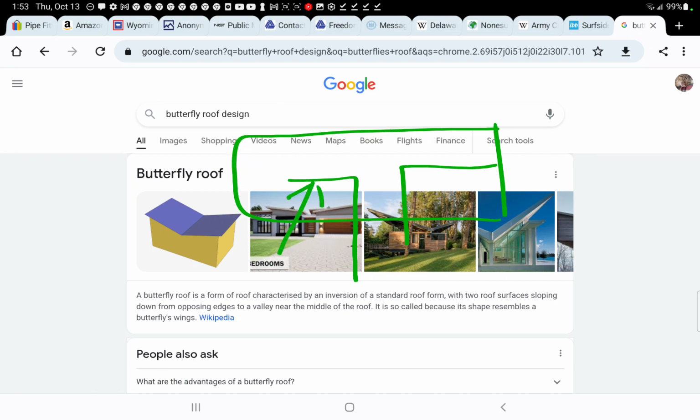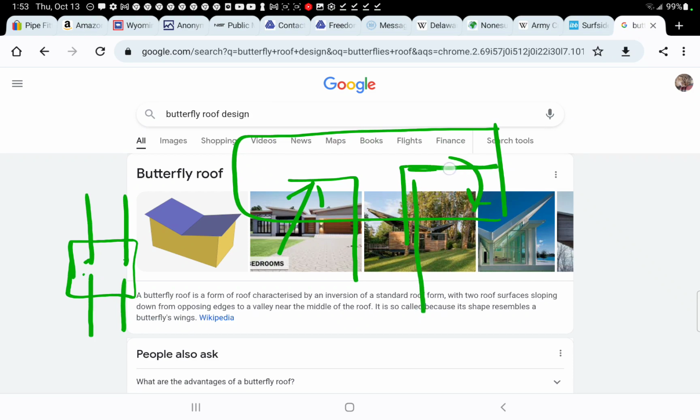But these only, if we're looking at it from top view, so here's top view of the column. And so direction matters, and then these are going down. And then this way, the direction matters. And as they were pulled down, the deck pulled down, here's concrete cover. As this rotated down with the deck, the steel did spall some of this off.